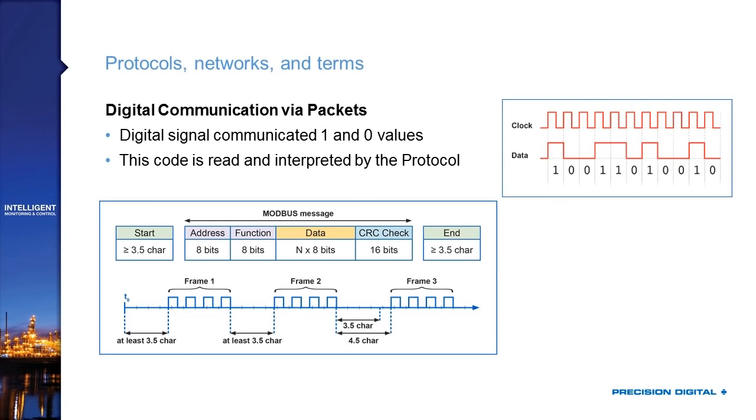And then what the device will then do is string together all those 1s and 0s into first a Modbus message, then into an entire Modbus packet. And now you're using these 1s and 0s, and you're transmitting out a lot of information digitally that the Modbus protocol explains to you how to decode.